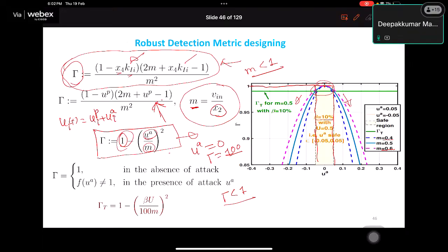That is why you require a secondary layer controller where the neighboring nodes at least communicate, because droop is very simple. Without communication, it can function. But at the same time, you should know the model so that you can tune your droop values appropriately, because the line resistance is not changing dynamically. Like today it is say 2 ohm, tomorrow it will not become 2.3 ohm. So it will remain the same.